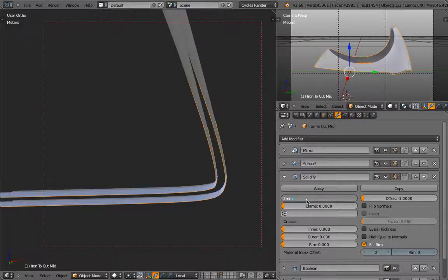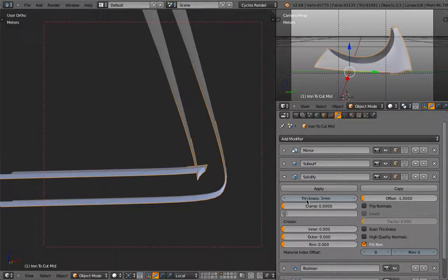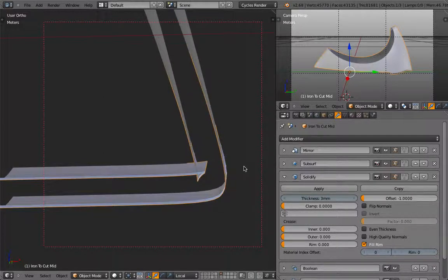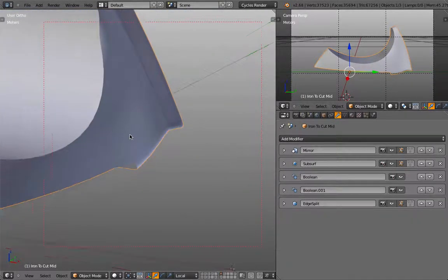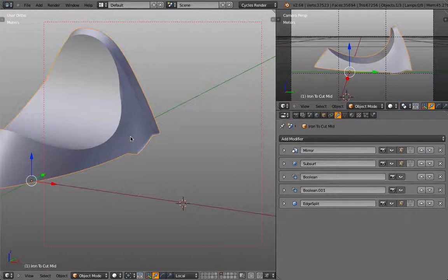So the problem we're going to face here is also this is not really good geometry. If we send this to the printer, the 3D printer will tell you that there are self-intersecting surfaces and cavities, and the printer is going to strike. So what we have to do is actually we have to construct this inner surface by ourselves.